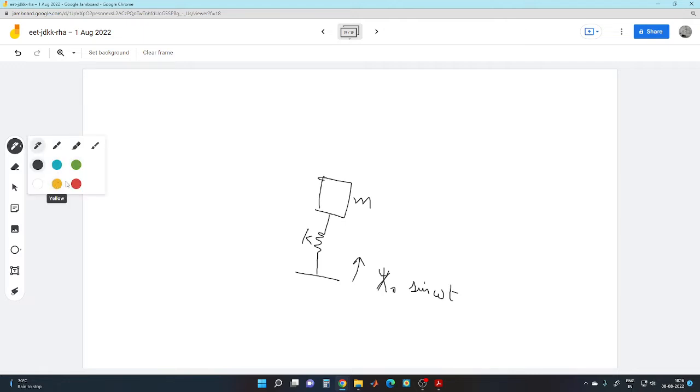What we want is to add a tuned mass, which is m1, with stiffness k1, so that if the vibrations are at near natural frequency, or whatever the frequency of excitation is, we'll later look into that, at that particular excitation frequency, the amplitude of vibration of this central mass is negligible. We don't care about this mass. This mass can vibrate at much higher amplitudes, doesn't matter. But this mass has to be at rest.